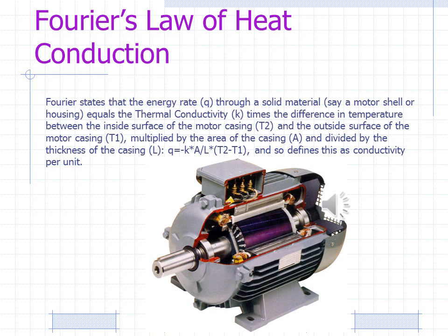If the motor has a fan on the non-drive end, as this one does, there will be outside forced convective cooling, which will increase the heat transfer to the surface of the motor casing, which will then give you a lower temperature on the outside, while the inside is still quite hot. But at least you're getting rid of it. That's what you want, the thermal conductivity out, to remove it. I've seen motors where the fan has been blocked and the motor is running at, let's say, 100 degrees C, only to run nice and cold at, say, 20 degrees rise above ambient once the block has been removed.